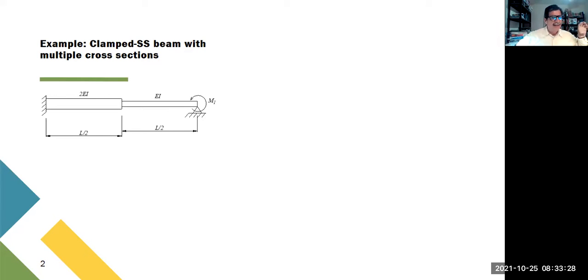And you see that it's not complex, it's just very long, because we have to integrate from 0 to L/2 and then get the displacement and rotations, then integrate from there to the right, and then at the connecting point, we have to set continuity of displacement and rotations. It's a very long process. And also shear force and displacement because it's continuous.